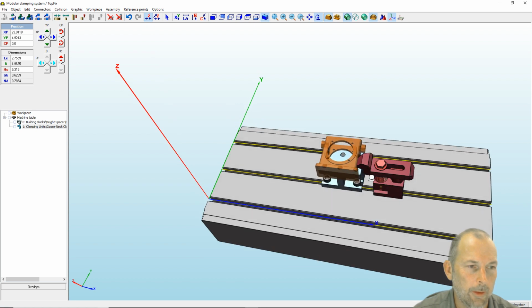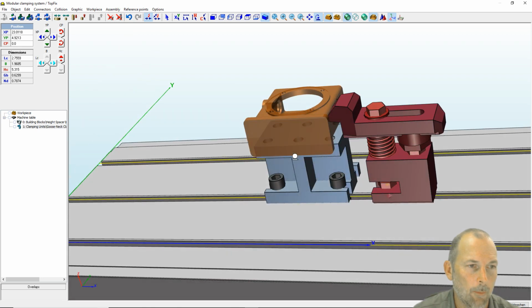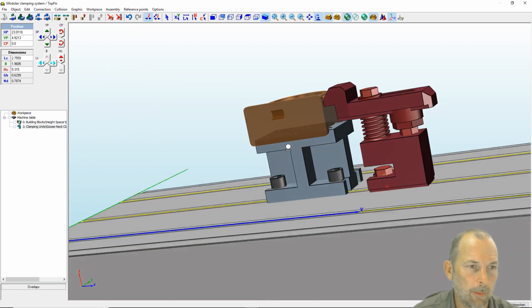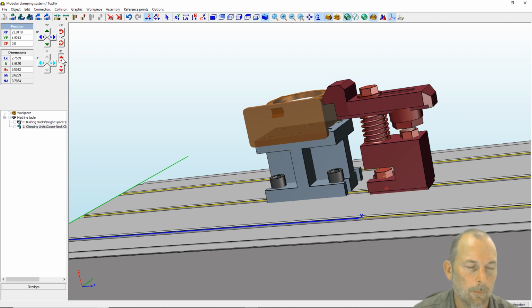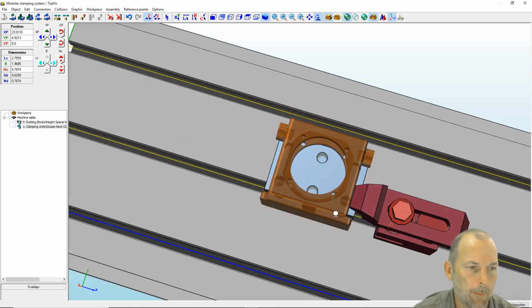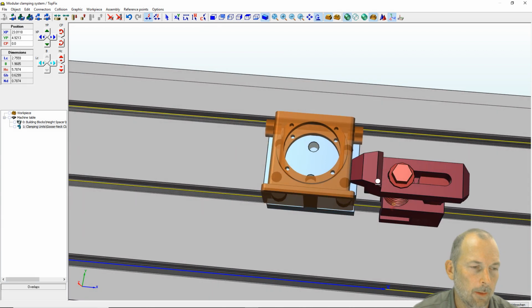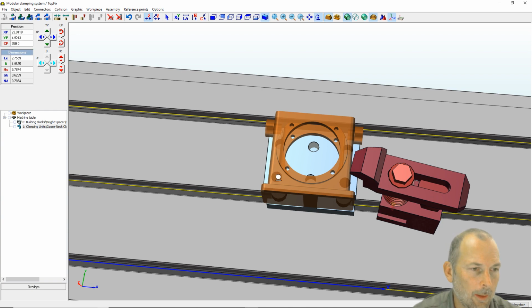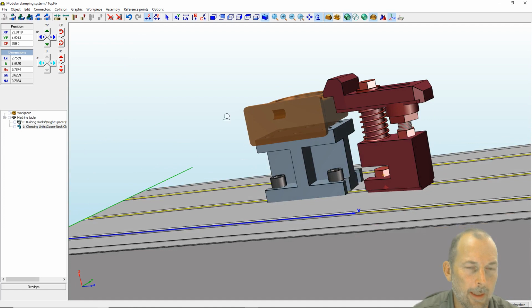So we've got a little collision there. I had left my collision with the workpiece on. And we need to raise that clamp just a little bit. And I think if we do the clamping right there, we're putting pressure pretty much off center. So let's rotate this clamp by about 10 degrees. So we'll change our C position. I think -10 might go, yeah, there we go. Now that gives us a little bit better angle on that part.